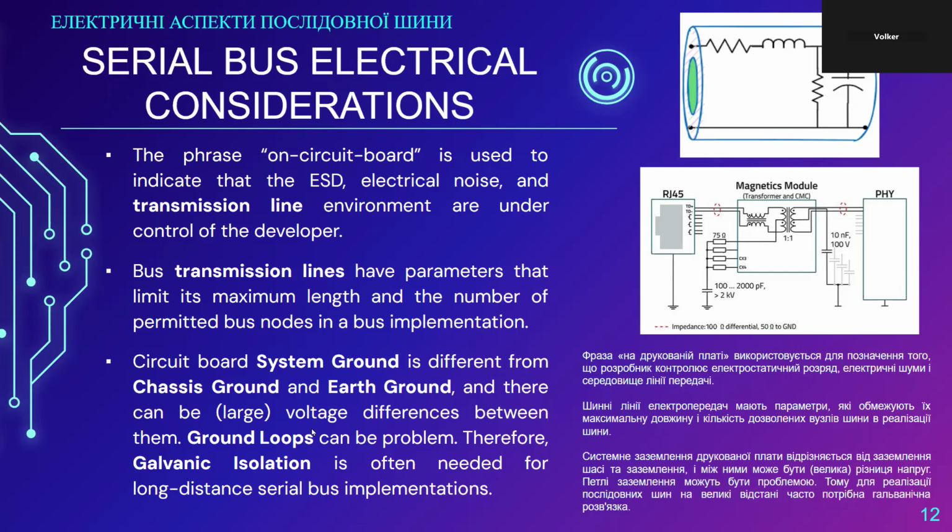There could be a potential difference of 230 volts. In order to avoid that, you need isolation. Generally, buses that might be connected to different earth grounds on both ends of the connection are isolated. Ethernet, for example, right from the start, was designed as an isolated communication bus.